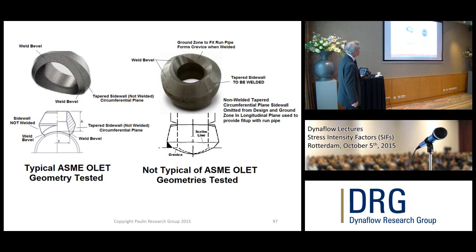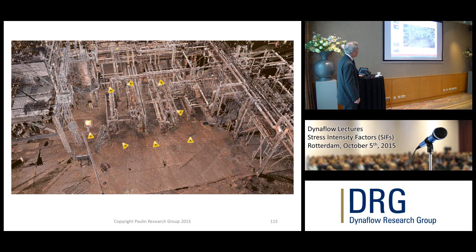Last but really not least is this. I think you've seen some of that. I hope that in the future, whenever anybody does a retrofit of any kind of piping system or a new piping system, you're very cognizant of the technology available with scanners today. Scanners have gotten so fast and so accurate that you can scan an operating condition, put it into the FEA Tools software, and tell it which Caesar models might match those deflections. The software reads the Caesar models and tells you which sustained and operating cases give the range that you see in the scanned results.